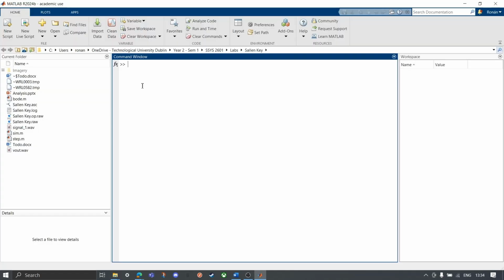Now that we have our step response from LTspice, what we're going to do is upload that to MATLAB. So SR, fs. We're going to be using the audioread function, audioread, and then it's called vout.wav, like that. And then we're adding the time domain as well. So it's going to be for the length of step response minus 1, and then we'll just divide that by the sampling frequency. Yeah. So if we plot them,